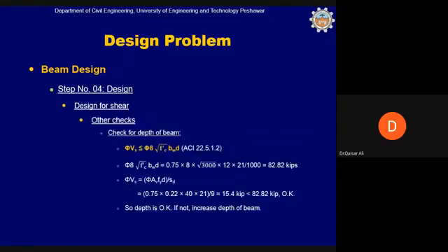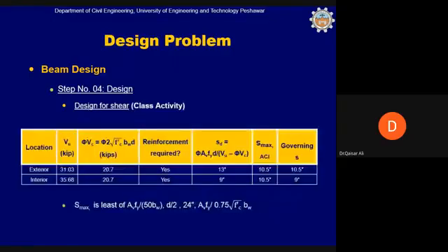Because the actual requirement is 10.5 and 9 inch, and there is only a difference of 1.5 between the two values, in order to simplify our design, we will provide 9 inch spacing throughout the beam, instead of changing the spacing for only this 1.5 inch change.